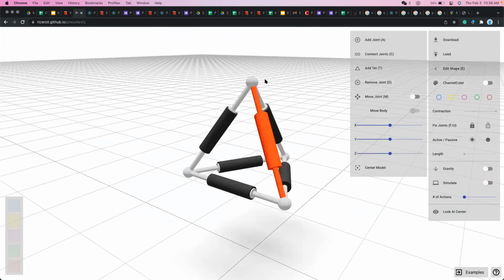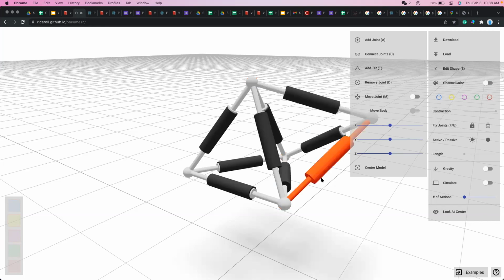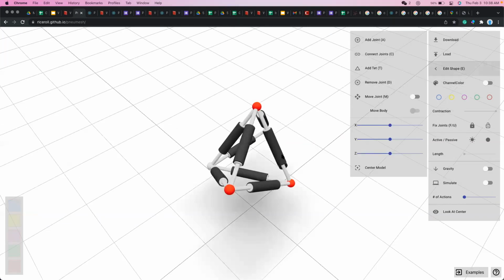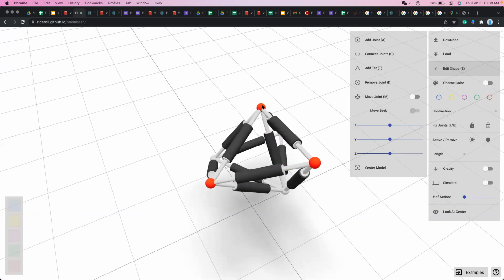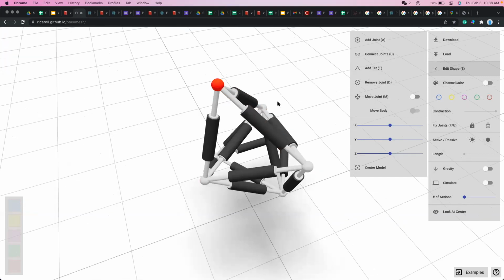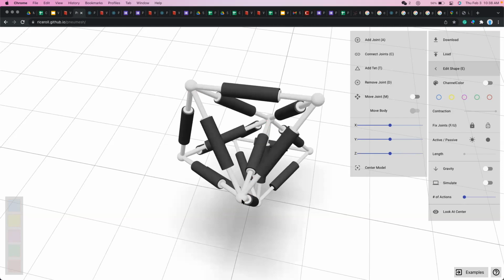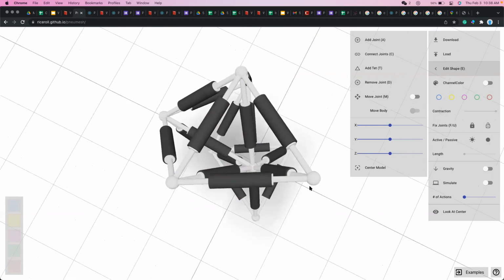What you can do is click 3 points and click add tetrahedron to add one, and you just iteratively do this until you turn this into a column structure. Because it's not like a cube, you cannot let it go all the way up, but there might be some twisting here. It is fine. It's just roughly looking like a column is fine.